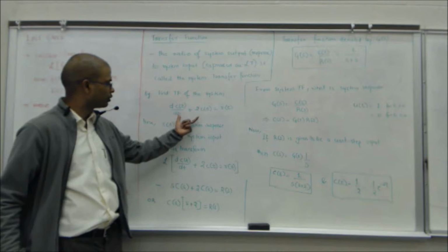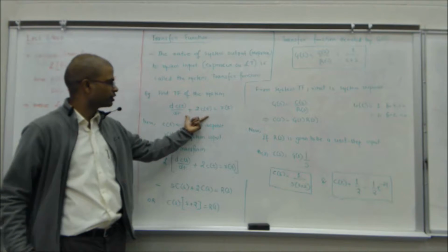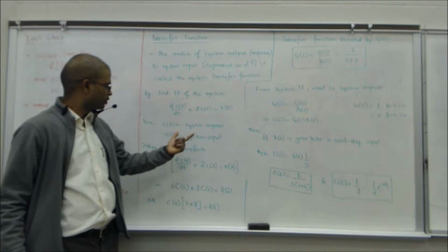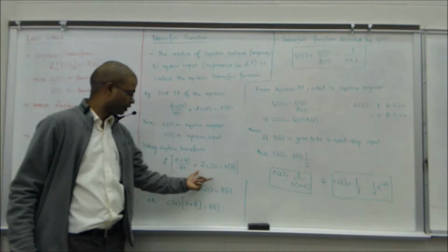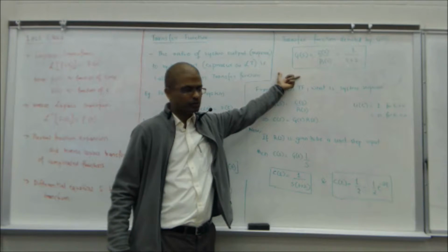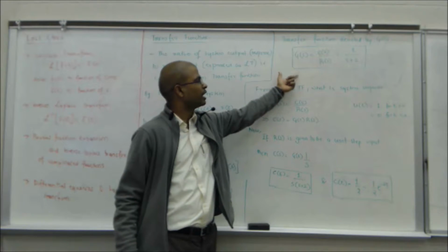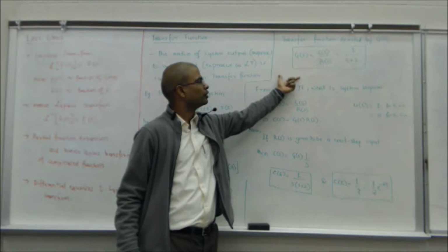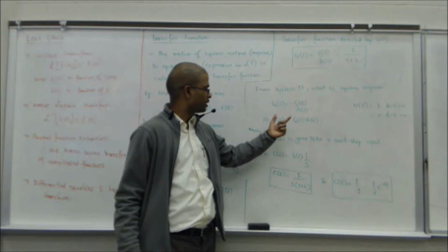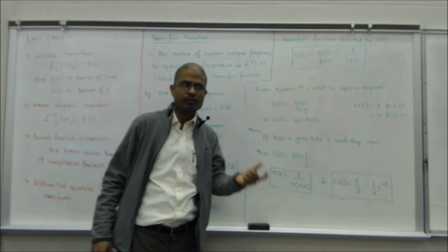So what we did here was we kept aside the differential equation solution. We said we'll look at this system, which is essentially an input-output relationship. We took the Laplace of that, found the transfer function, and then said, let's analyze this system for a step input, or find the unit step response.